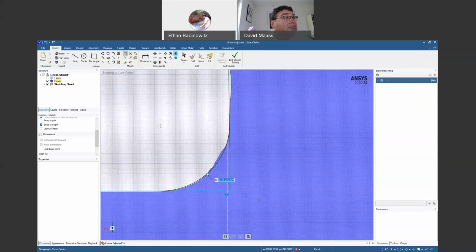And that little green dot is snapping it to the sketch here, and I could always type in a value if I want to round it. Based on the number that we're seeing, I might be in the wrong unit system when I imported the STL, because STLs don't have a unit system. So I don't want to interrupt this process, because we could scale it to size later on.